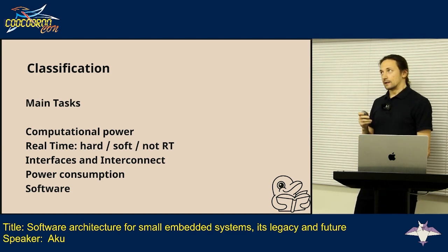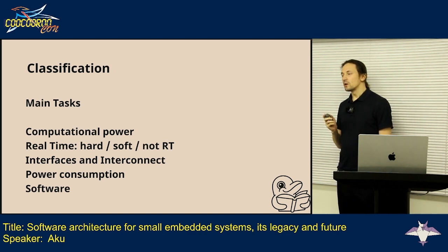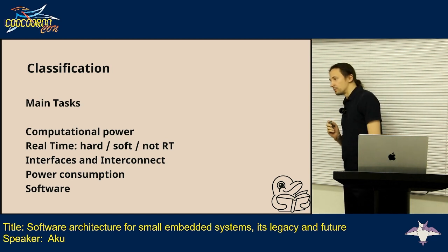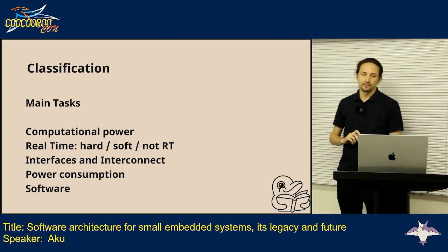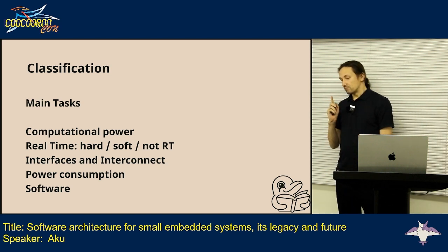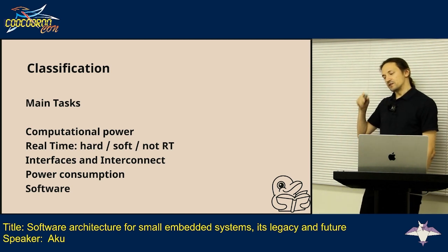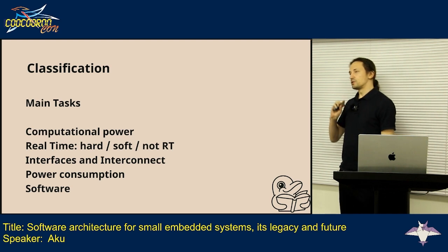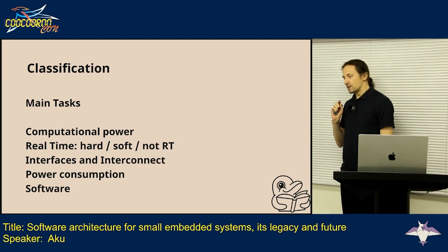And that becomes a little bit difficult because not all architectures were designed to be power efficient. Some architectures simply miss any power saving features. And if you get specific requirements like, okay, I have an embedded system that should last, let's say, 1 year with a battery, then you probably would like to choose appropriate architectures and hardware for it.